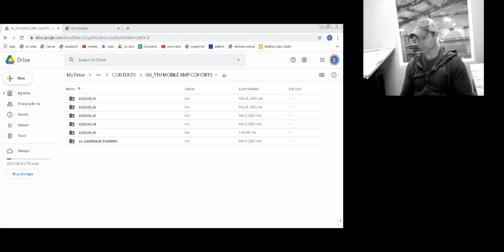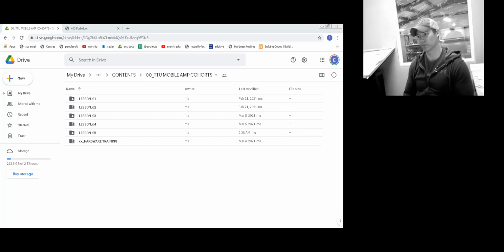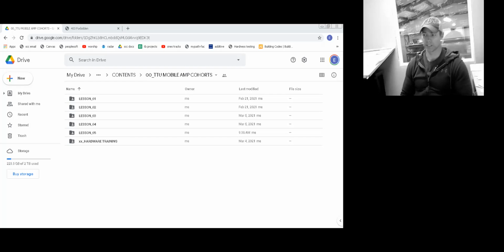I found a nylon filament. Do you think this Genius printer can handle the nylon? It can. We've printed in nylon quite a bit. We've printed with TPU quite a bit with the Genius. The catch is you just have to change your settings. You'll have to make it go slower. And higher temperature, right? Generally, yes. Higher temperature on your build plate, slower speeds.